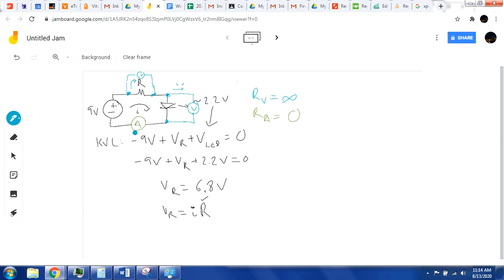I would want it to just measure the pressure difference there. Same goes for the ammeter. If I wanted to measure water flow through a pipe, I would want it in series so that all the water going through here goes directly through my flow meter. I would want it to provide as little resistance as possible. I'd want it to look just like this straight section of pipe so that I'm not restricting the flow at all.